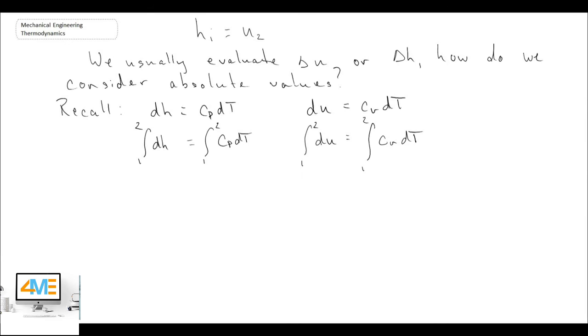However, for this particular problem, we have been told that the values are constant. There are other gases where the specific heats are constant, and these are argon, helium, neon, krypton, xenon. So those are gases where we have a constant. Now we're dealing with air, which normally wouldn't be constant, but we're told as part of an approximation for the problem that we should assume that.